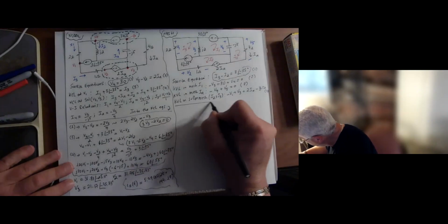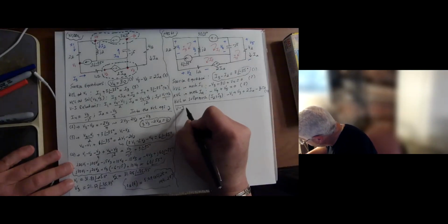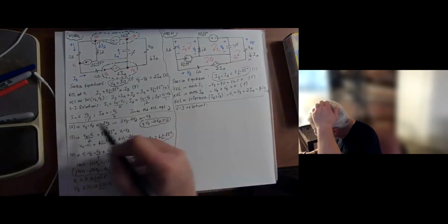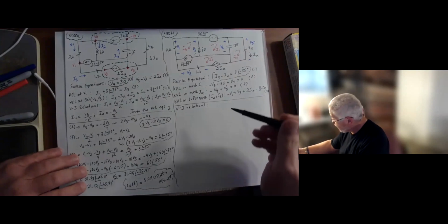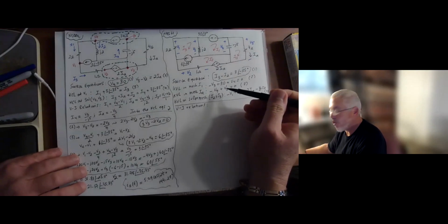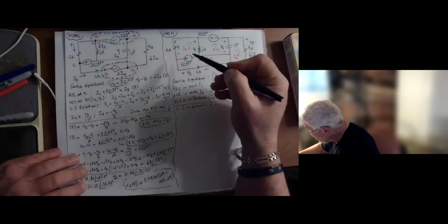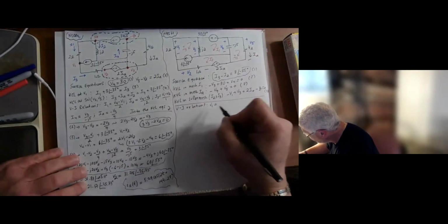And now, VI relations. You can see the parallel that I'm drawing here. What the VI relation does is allow us to write the voltages in terms of the mesh currents, which are the unknowns. So V1, where is V1 here? Again, you have to pay attention to the passive sign convention. So V1 is minus 2I3. V2 is minus I2.